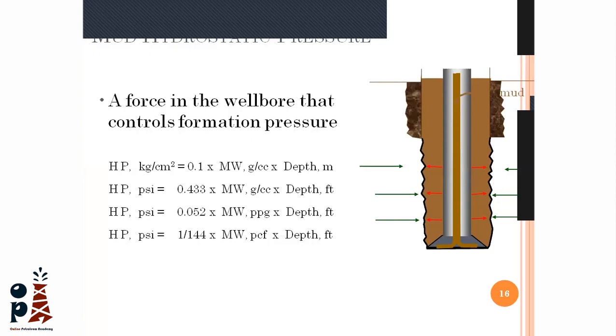Guys, think about it, because it is somewhat difficult to imagine. But imagine that you put a pressure gauge at the bottom of the well. At static condition, the bottom of the well just senses the weight of the mud column. But what about the dynamic condition? There is a pressure loss at the annulus due to friction. So when we put a pressure gauge at the bottom, we will sense a higher pressure. This higher pressure in the dynamic condition is affecting the formation, affecting the bottom hole pressure.